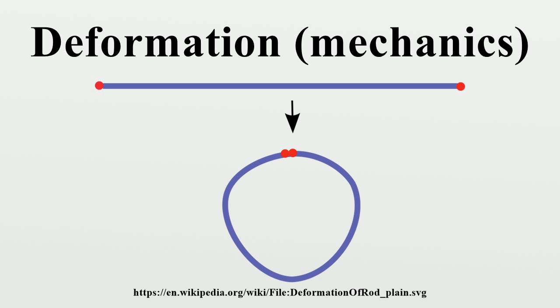From the geometry of the adjacent figure we have, and for very small displacement gradients the squares of the derivatives are negligible, and we have the normal strain in the direction of the rectangular element defined by. Similarly, the normal strain in the other direction is defined, and the remaining term becomes shear strain, the engineering shear strain.